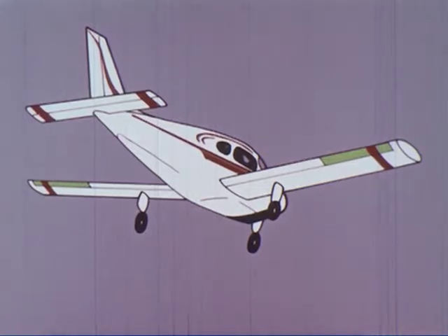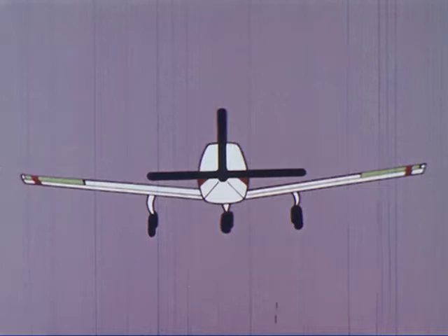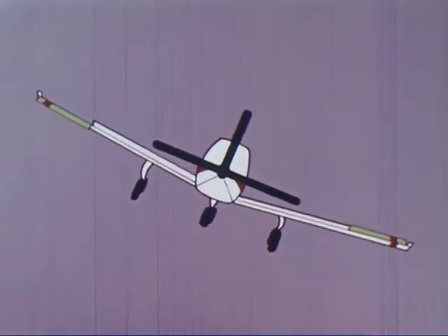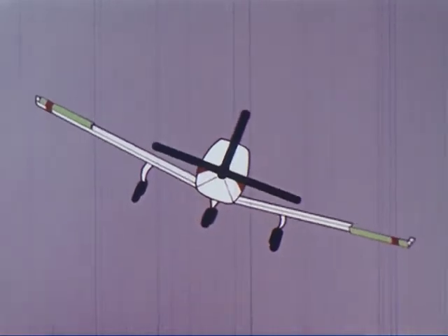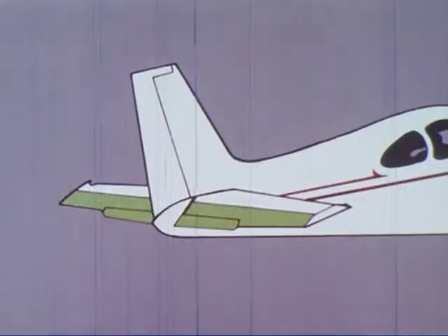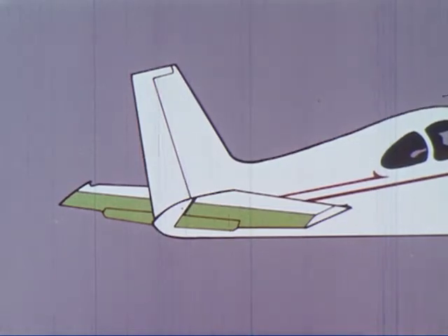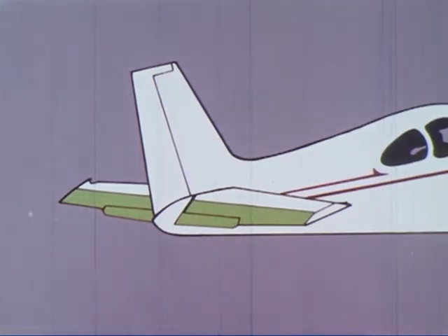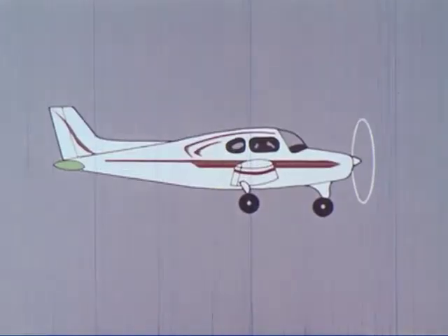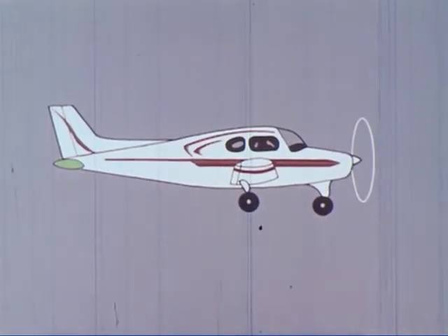At the rear edge of the wing and near the wing tip, the ailerons disturb the airflow, and by moving in opposite directions, simultaneously lift one wing and lower the other. The elevator at the rear of the stabilizer disturbs the air in a similar manner. This entire control surface moves in the same direction, either up or down.